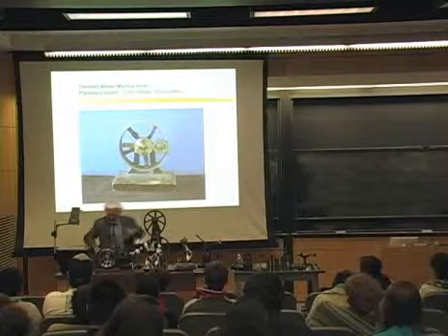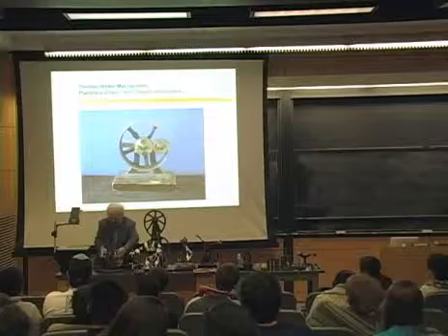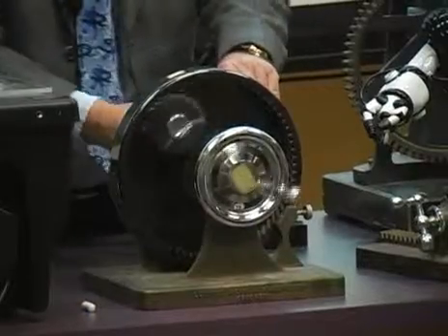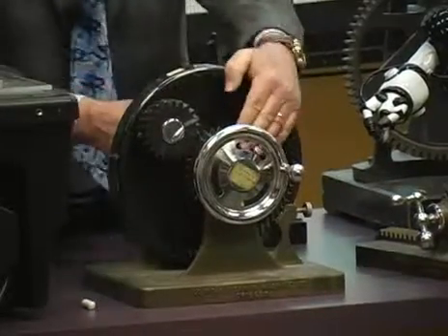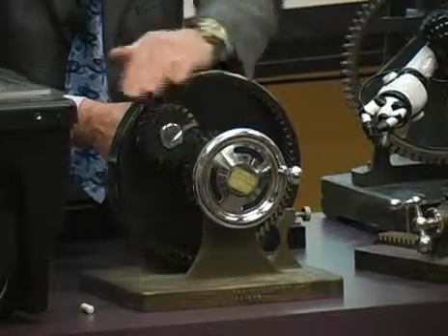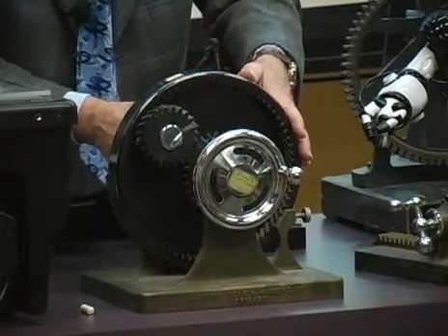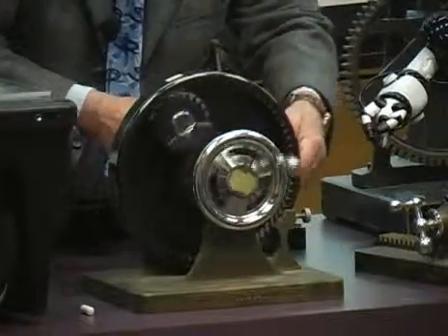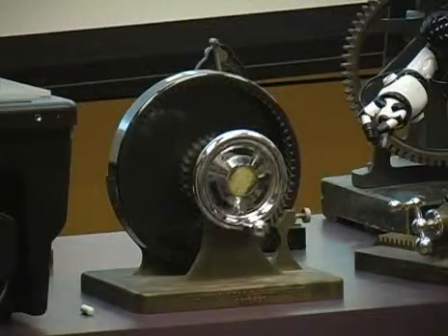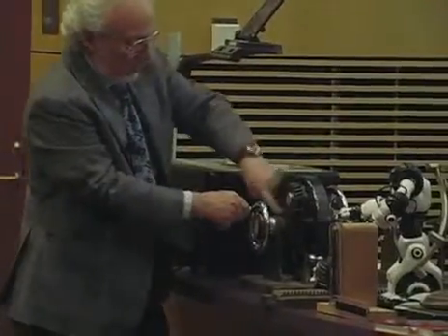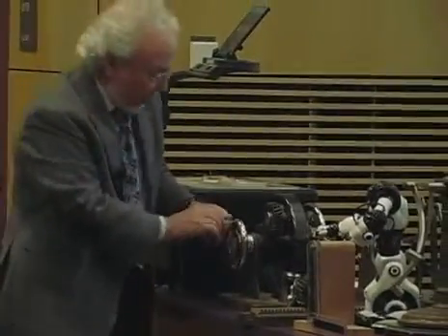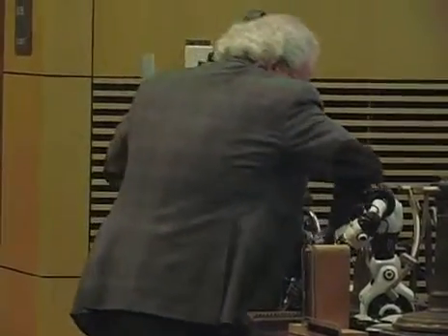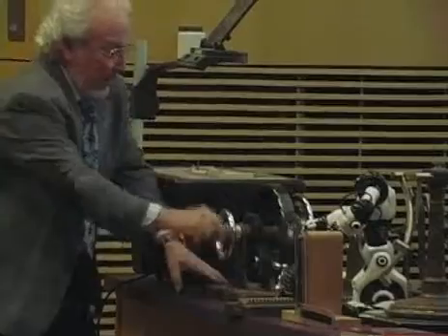planetary gears. Now here's one here, which is a so-called planetary gear, and you can see here that it's called planetary because the gear in the middle is called the sun gear. This is called the planet gear here. This outside here is called a ring gear, and you can have the input this way here, or the connecting link here is called a spider because often there'd be 3 or 4 of these. But you can also lock the spider, and now you can have the ring gear move.